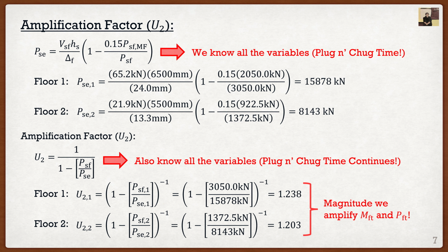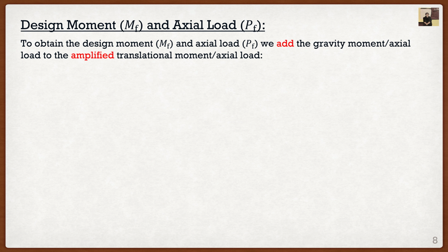But one little thing before we actually do that on the next slide, just notice that we are only amplifying the translational moments and axial load. We are not magnifying the gravity moments, just the translational. So this leads us to the end of our problem, which is actually determining the moment and axial load, or the design moment and axial load of our frame.